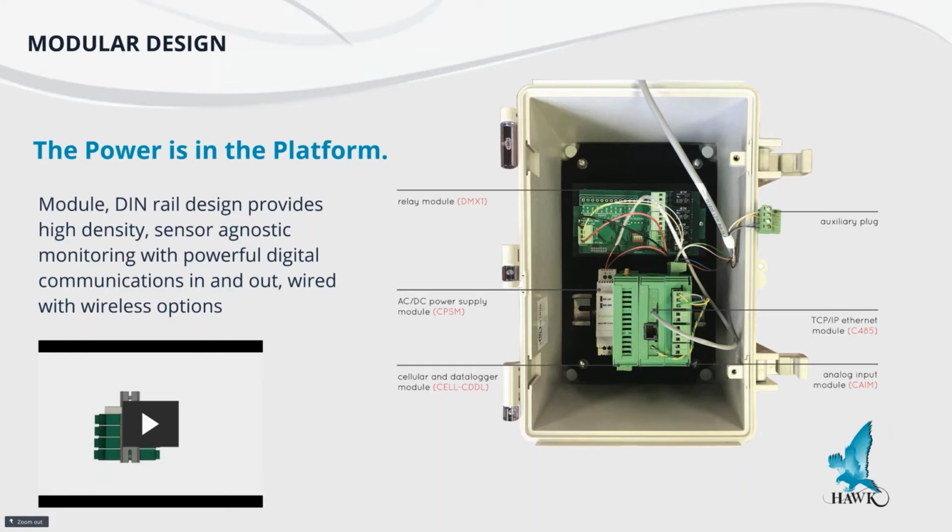One of the considerations in designing a system is whether I can connect to literally any device, whether it's already existing or may not have been designed for data collection and data uplink. If I can bring those field devices into my monitoring system, then I won't be required to go out and purchase any sophisticated or selected types of field devices.